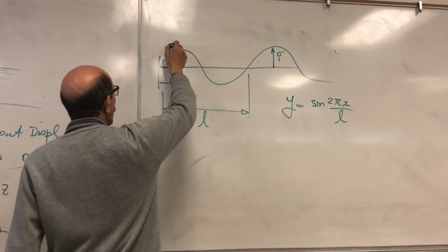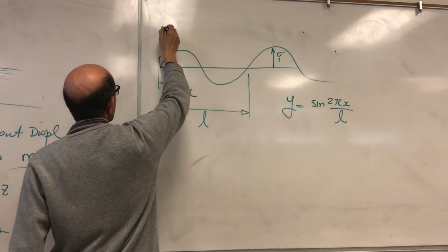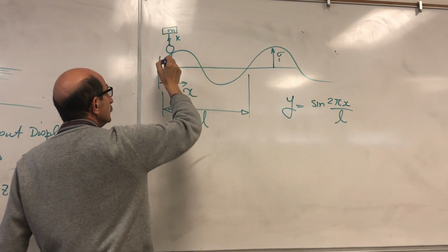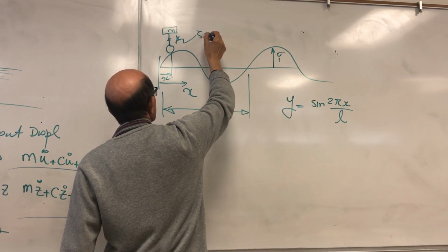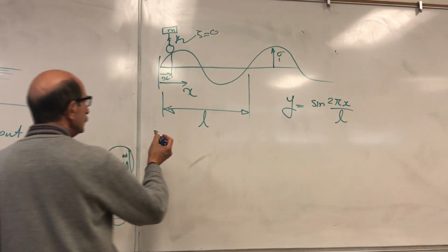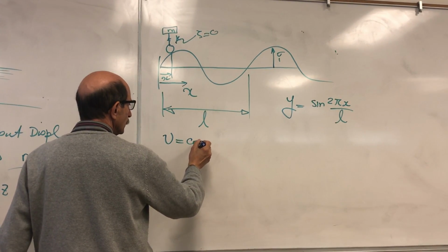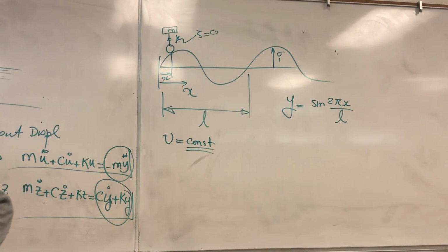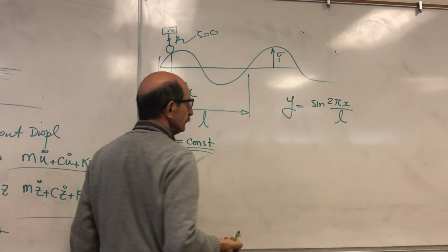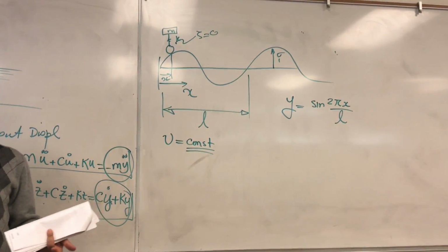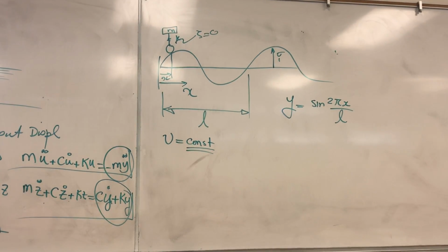Now, let's assume you have a car. To make the case simple, your car is traveling, and there is no damping, so assume that this is an undamped system. And if it is moving with a constant velocity, we want to find the most unfavorable or undesirable velocity of your car under these circumstances. So given that the input we know is harmonic, and given that we know the system is undamped, what would be the most unfavorable speed?